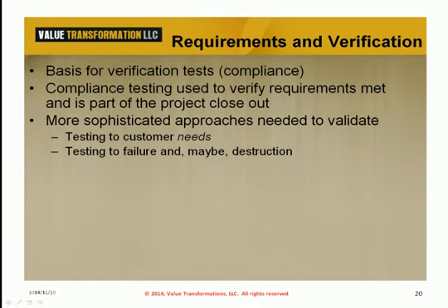Compliance testing comes from testing specifically and exhaustively, to the extent possible, to requirements. It is the baseline for all subsequent testing, but by no means is compliance testing ever enough testing. Customer reliability requirements are extremely difficult and costly when we test for reliability. The reliability formulae have inbuilt assumptions that can significantly affect the result, for example, the exponent in the Arrhenius equation. The supplier should consider alternative approaches such as highly accelerated life testing to elicit failures, rather than rely on potentially specious predictions of life.